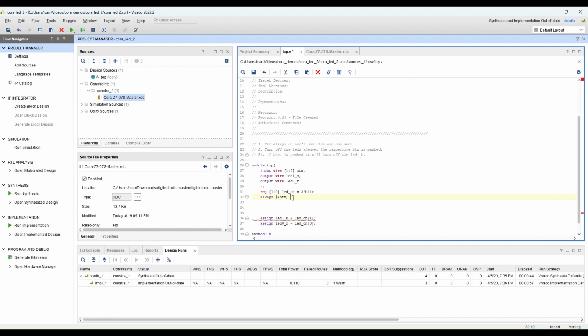In the next episodes, we're going to have the value inside of here be the positive edge of a clock, so that every time it's on the positive edge of a clock, it will run a certain code. And so in here, we're going to do begin and end. That is how an always statement is set up.